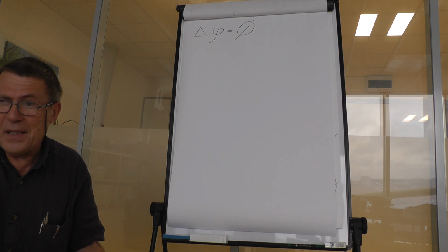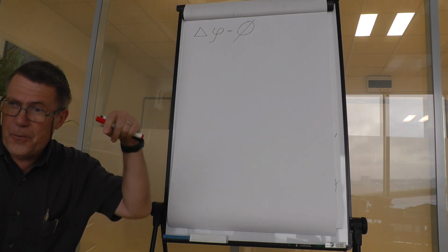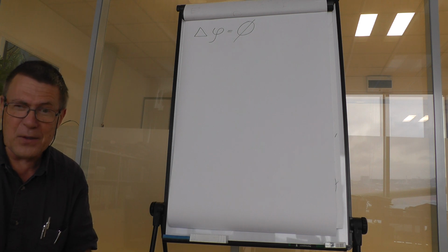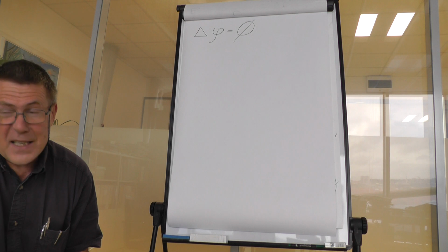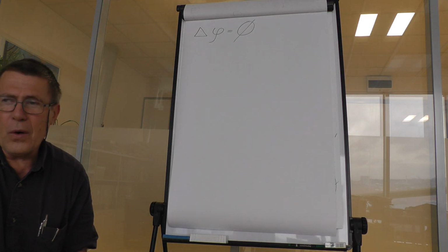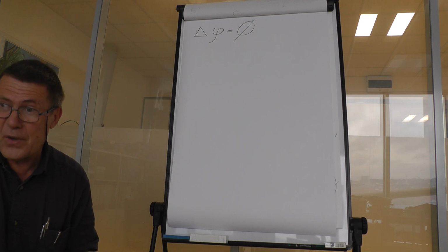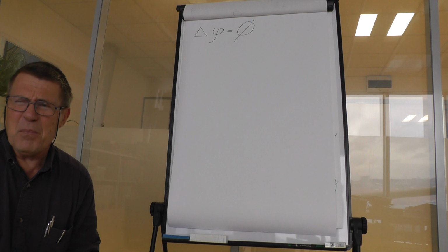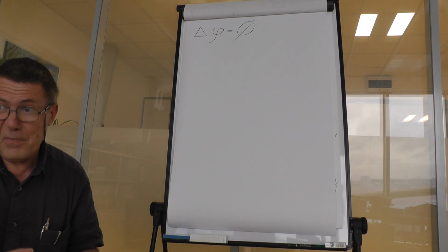You have quite thick electrodes, a lot of transformers, three-phase sources feeding the current into those electrodes. And as that's something very expensive and you need to get more or less homogeneous temperature in the furnace, it needs some calculation or some analysis before you build it.